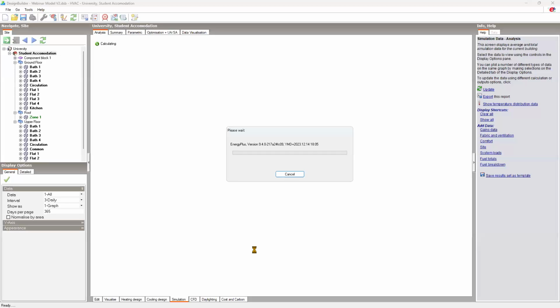In this simulation, I'm only interested in the fuel breakdown at an annual level. So I did not ask for more detailed outputs, such as what's happening with internal gains or various surface level outputs, comfort, environmental results, etc., at much higher granularity, like hourly, sub-hourly. I would have done that if I was analyzing the building performance in more detail for a real project. It's also good practice to do proper QA checks of your models before you embark on final runs.